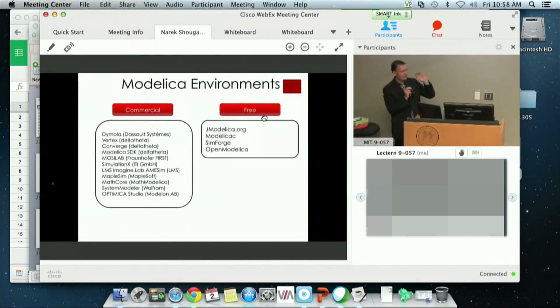So you heard about the general idea of system modeling languages that are rigorous, that have ontology, syntax, and semantics. There are different ones of these that have been proposed and developed. Some are used more than others. There are really important differences between them. So OPM is very conceptual. SysML is based on UML and has different types of diagrams and can really help you flesh out your design in more detail. And then Modelica allows you to build these blocks. It's acausal or declarative, and you can actually simulate the physics of the system pretty readily.